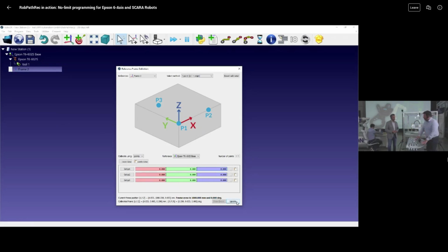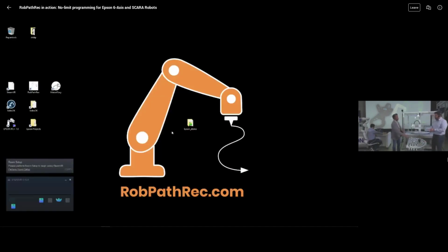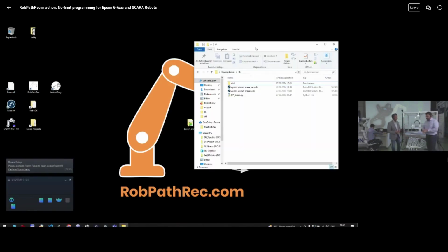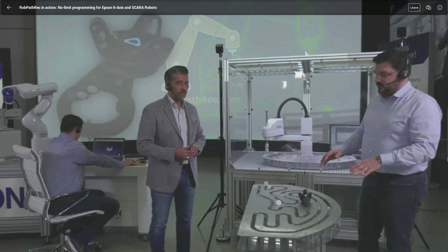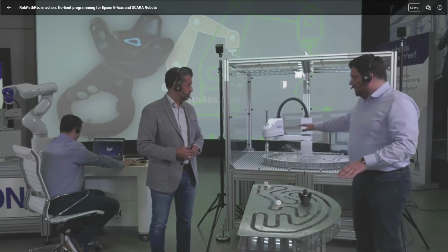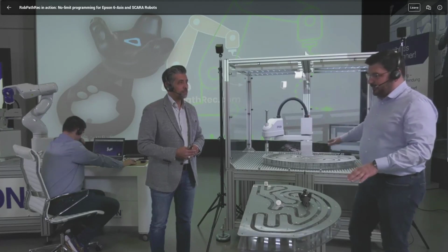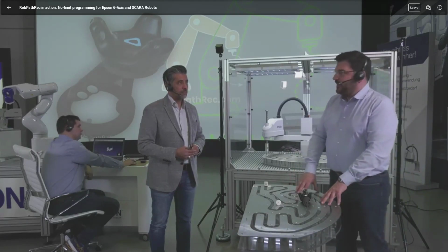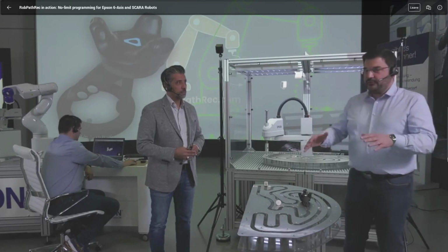Yeah, so we are lucky today that we have the two paths doubled. But there is an advantage in the background. Why do we show this not directly on the robot, but here outside of the cell? This is one of the biggest time-saving potentials you can reach, especially with your industrial robots. Just imagine you could measure or define the whole working area of the robot, and then do the programming offline anywhere. That means your robot is running productively all the time while you are doing the programming. So you don't have to stop it for manual teaching or anything else.